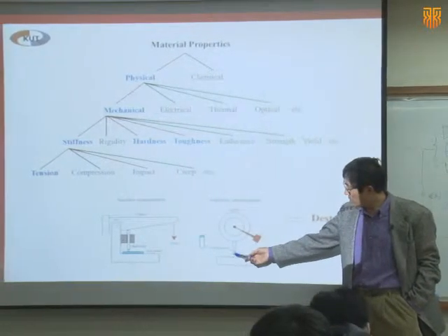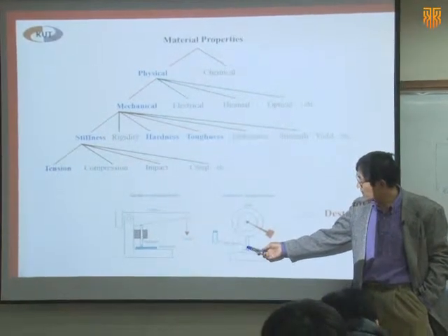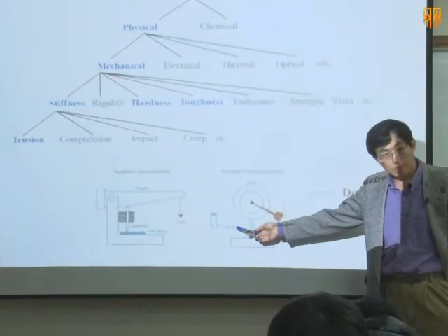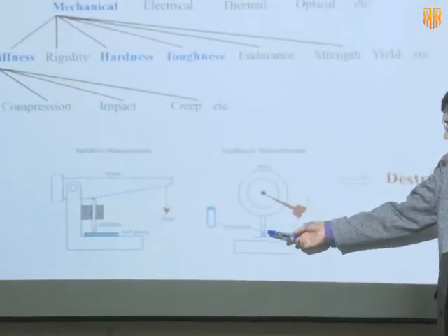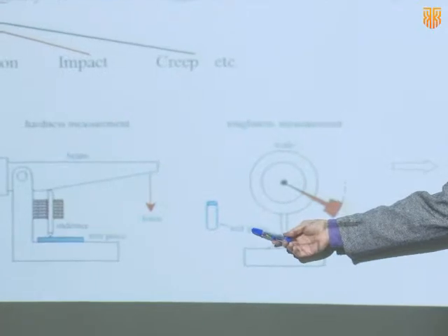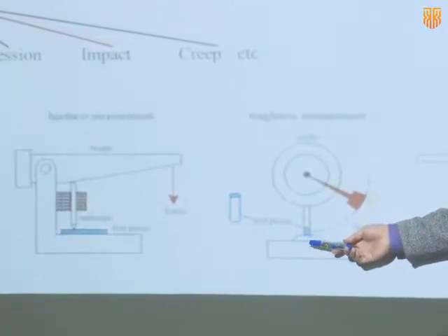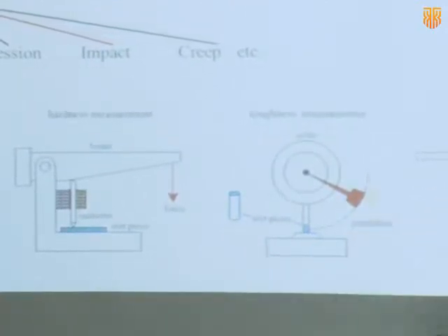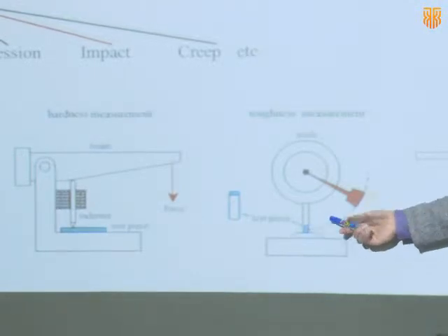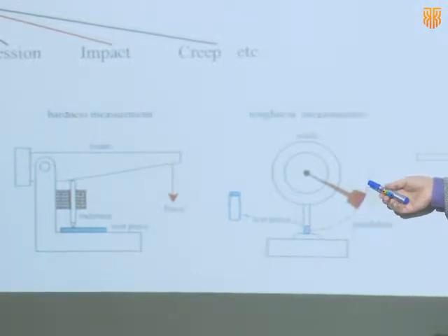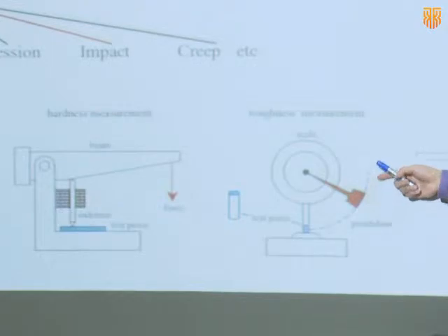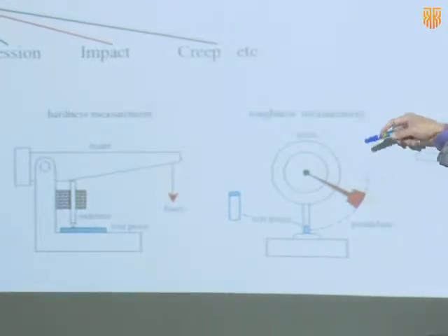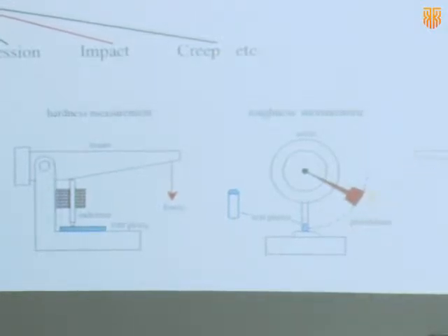If you want to know how hard or how tough the material is, you put the material of your interest in this position. You can put it in the hole, and then you hold this hammer and release it at some point, and then this hammer returns to the position and hits the material, and then it breaks, right?